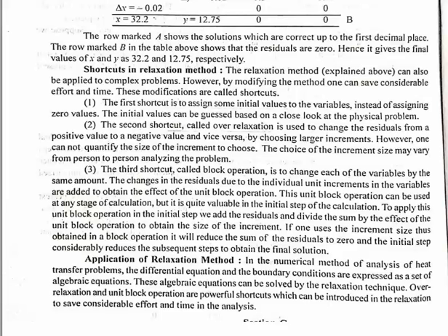Now, what are the applications of the relaxation method? In the numerical analysis of heat transfer problems, the differential equations and the boundary conditions are expressed as a set of algebraic equations. The algebraic equations can be solved by the relaxation technique, and over relaxation and the block unit operation are the most powerful shortcut ways by which we can apply relaxation to save considerable effort and time in the analysis.